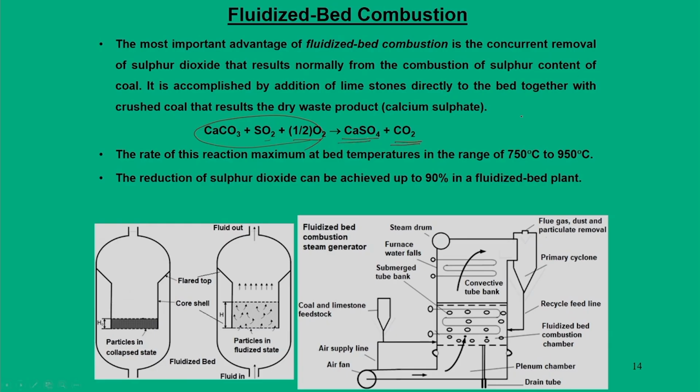CO2 anyway goes out to the atmosphere. The calcium sulfate is collected as dry waste. This is how the limestone helps in capturing the sulfur, so that SO2 formation does not happen in the end.